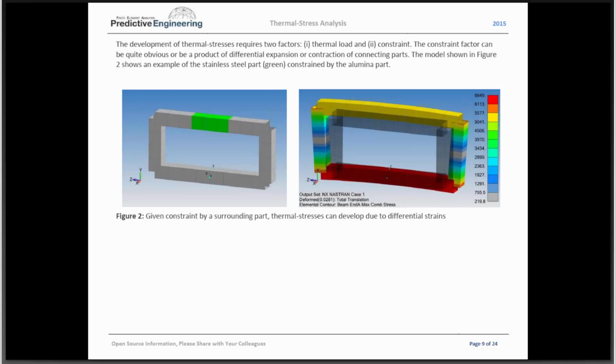Adrian, did I miss anything? I think that's good. For anyone getting into these problems, this type of model is exactly what you want to start with. George and I do it, and we recommend everyone do it before you tackle your big assembly. Build something with some beams, just a few elements, and sort it out like this. It's very insightful.